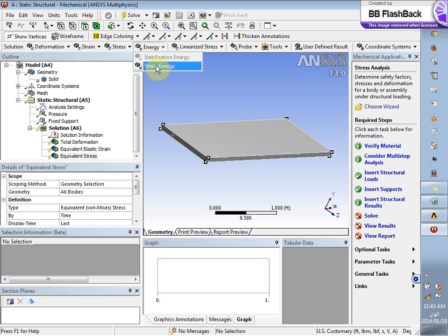At the end of the analysis, those all appear to be zero. If there is cracking going on, deformation, then the total energy becomes less, because some energy is wasted in cracking. So you will see that strain energy is reducing.